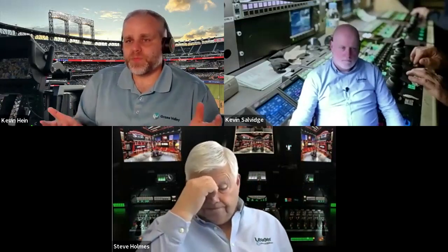And in fact, it's interesting to see we within Grass Valley, when we had our cameras, when we actually sent signals from the cameras to our XCUs, our CCUs within Grass Valley, all of our cameras since 2012, 13 are IP-based cameras, and the majority of our customers are not aware. And what we're using in some of those is actually TICO, which is the predecessor of JPEG XS in a 4:1 compression. So some people say, oh, it's compression. But when we look into the compression levels, and I think that's one of the slides we will talk about, that actually JPEG XS at 10:1 is visible lossless. So 4:1 is absolutely perfectly fine. You will not see any problem, but you have a drastic improvement on bandwidth requirements.